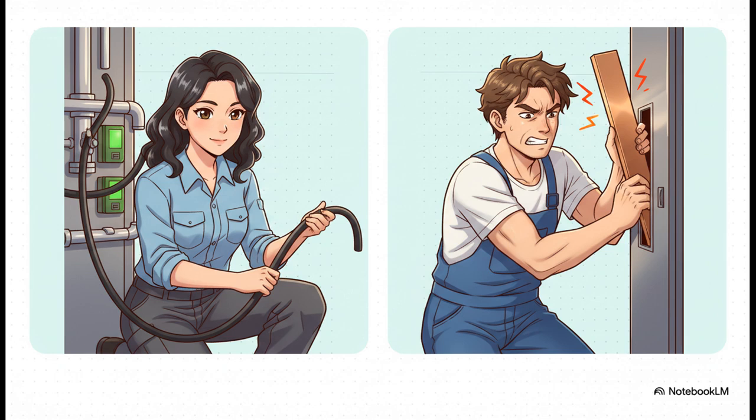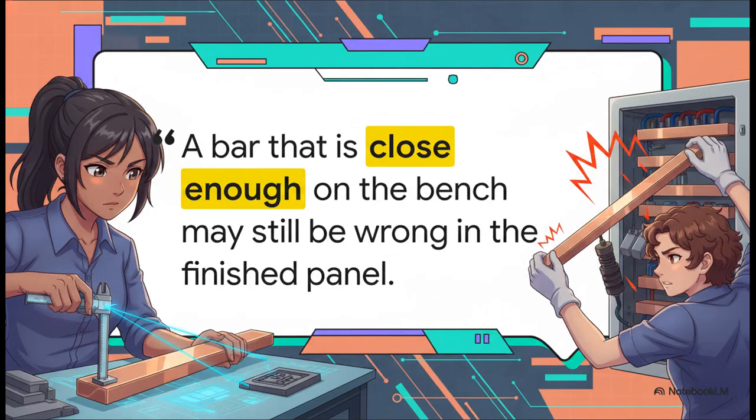If your pre-bend blank length is wrong, you simply can't stretch it. That little mistake instantly becomes rework, extremely expensive scrap material, or honestly, worst of all, it turns into mechanical stress because an operator forced a poorly fitting joint together. So the takeaway here is that dimensional discipline isn't just a nice to have, it's totally mandatory.